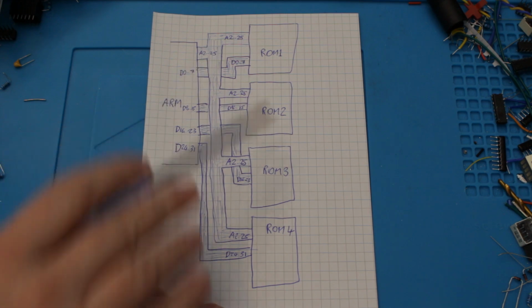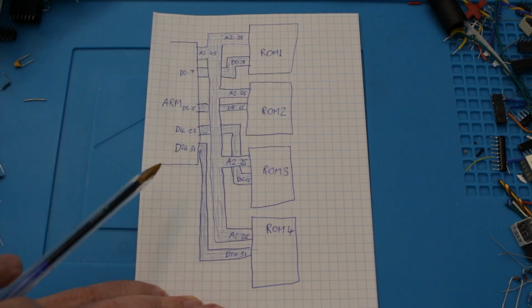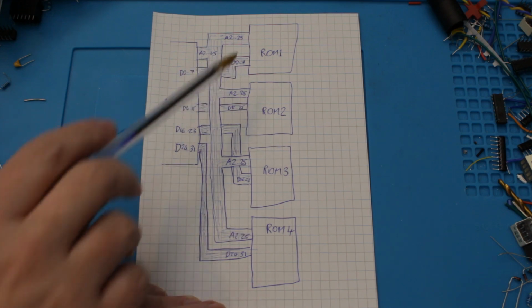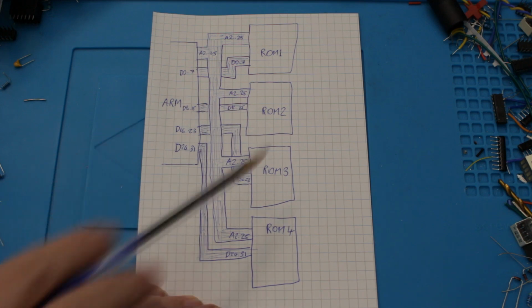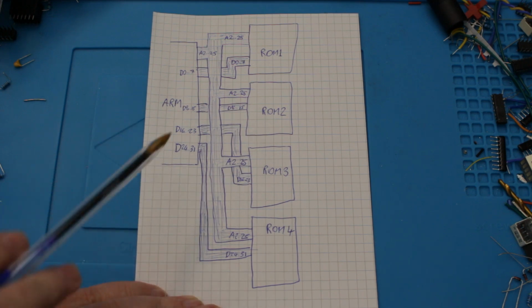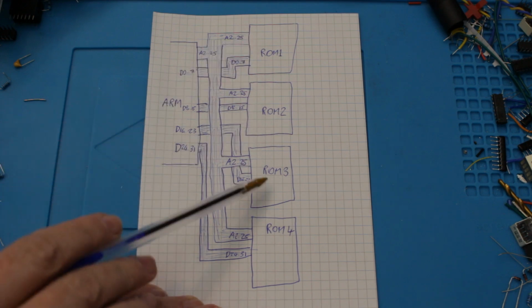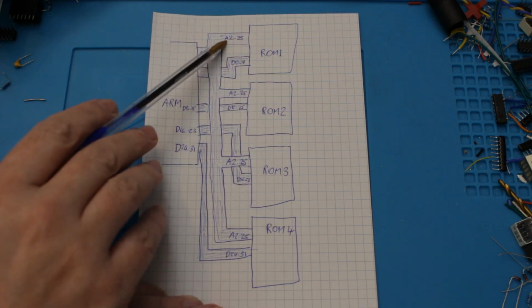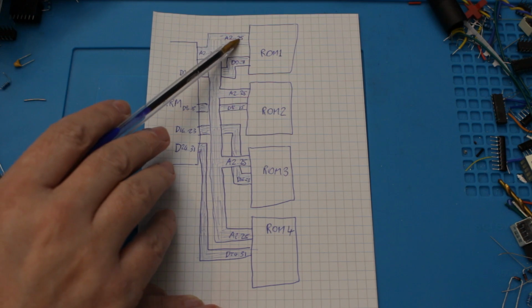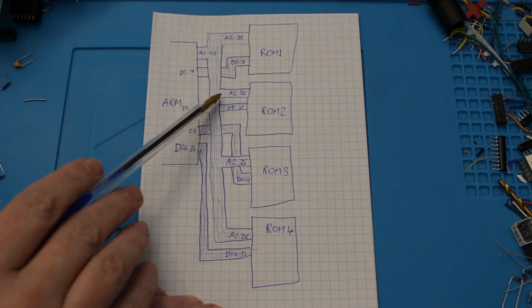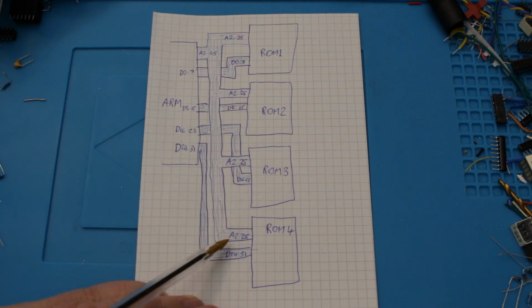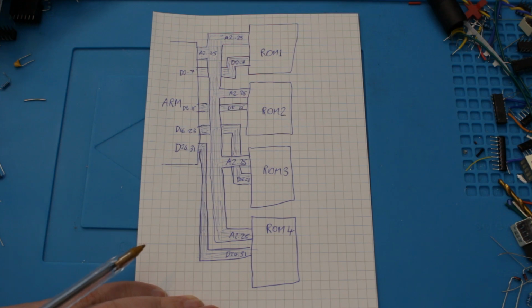So I suspect this is how the ARM designers intended the setup to work for ROM. It certainly seems likely given that the original Acorn RISC PCs and Archimedes had 4 sockets for the OS ROMs. It would make a lot of sense. It's probably the simplest way to do it. What we have here is all 4 ROM sockets have the same address pins mapped to them. That's address pins 2 upwards. I put 25 here. They may not have all 25 pins connected. But all 4 ROMs receive exactly the same address on any bus cycle.